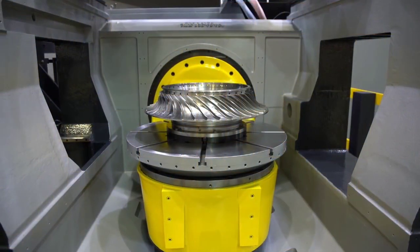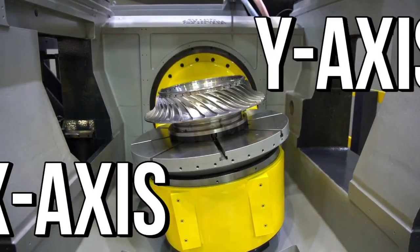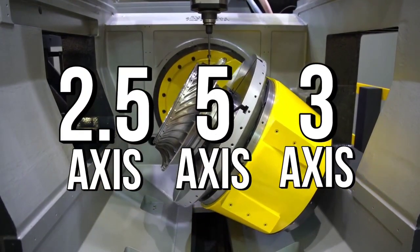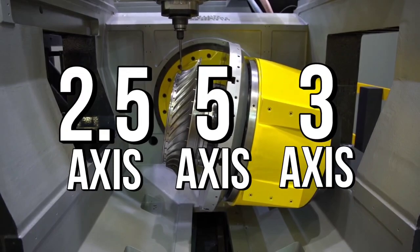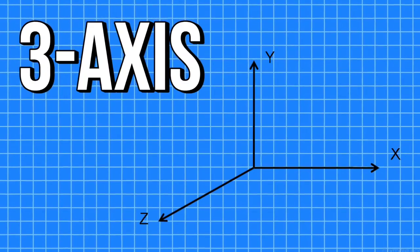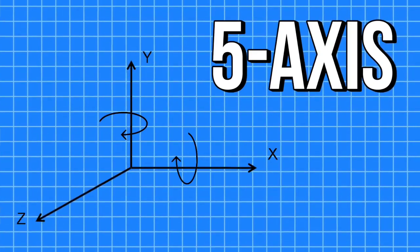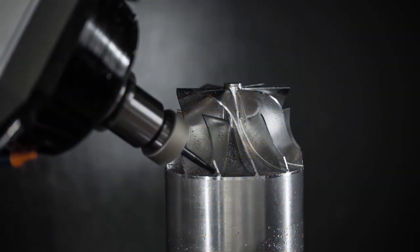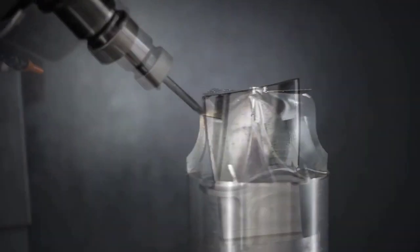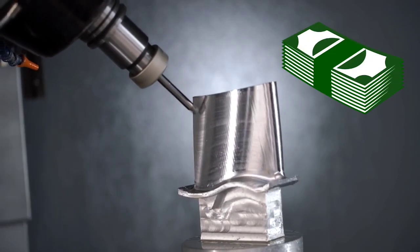Basic CNC machining will move one or two axes, referred to as the x-axis and the y-axis. You'll often hear the terms 2.5-axis, 3-axis, and 5-axis CNC machines, which simply refer to the degrees of freedom a machine can make cuts in. A 3-axis machine will move in the x, y, and z axis, whereas a 5-axis machine can move in these 3 axes along with 2 additional rotational axes. As you might be able to imagine, the possibilities of production with 5-axis machines are practically endless. 5-axis machines used to be relegated to high-precision work, but as they have become more affordable, they are quickly becoming